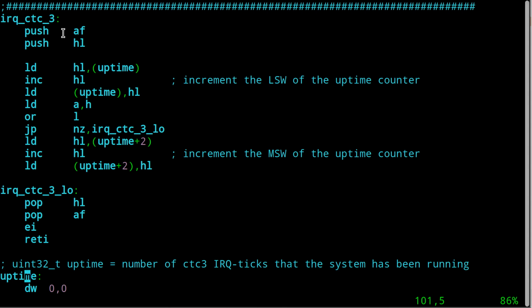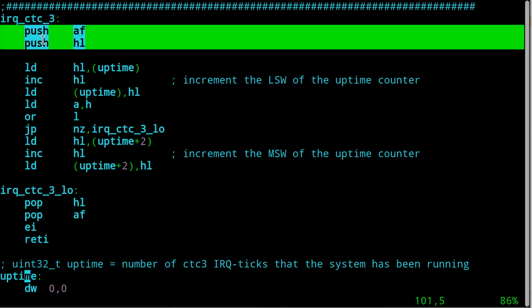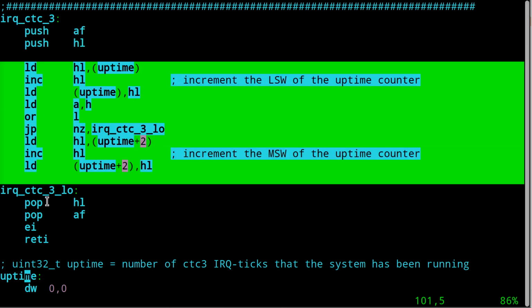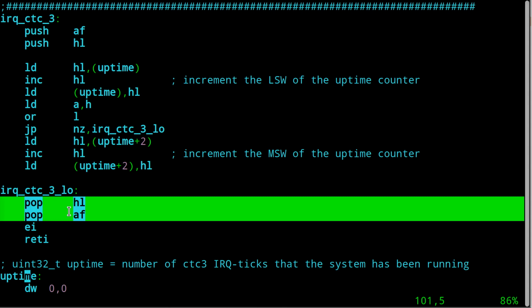Okay. Now, what's going on up here? When you get an interrupt, think about that. Remember, what we're doing is interrupting any code that might be running when the interrupt arrives. In this particular example, our intent is for it to interrupt the halt instruction. Arguably, it's not doing anything of value. However, it could be doing something of value. So we need to save all the registers that we might modify in our interrupt handler so that we can then restore them again before we go back and resume the program that we've interrupted.